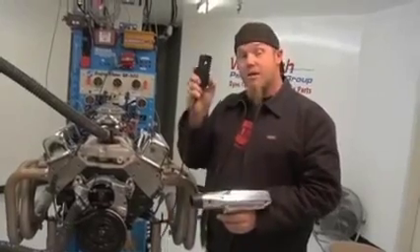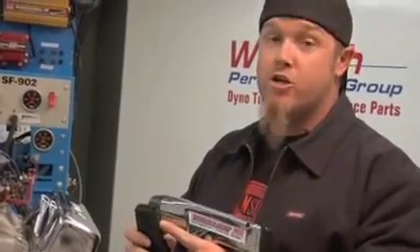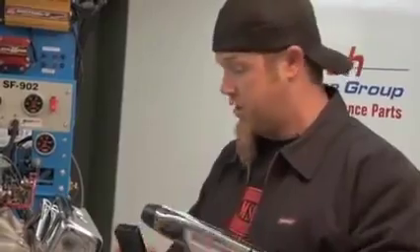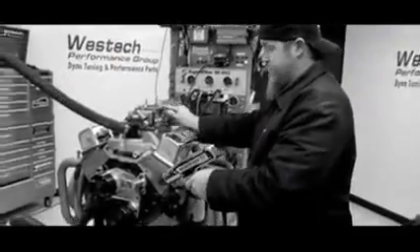And then also take this pickup and hook it to your number 1 spark plug wire. You'll note that on some timing lights, there's an arrow that points in the direction of the spark. In other words, that arrow needs to point at the spark plug. You hook this up to the number 1 spark plug wire. Every time the number 1 spark plug fires, this sensor picks it up, creates a strobe effect with this light so that you can read the timing mark on the balancer.